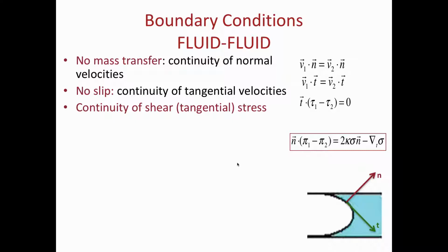Now, if I'm in a situation where I'm at the ocean and we've had hurricanes blow through, right? So I have shearing at very high velocities. Well, then my velocities are not that small. So even though I have air, that equality is not going to necessarily be true. So I don't necessarily apply this zero shear stress situation.